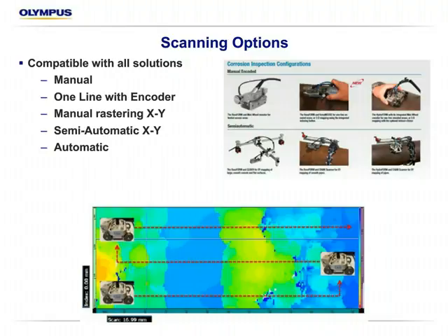And then we have more dedicated scanners, so link-based scanners for piping systems as well. Those are typically semi-automatic, in the fact that an operator will drive the scanner around the pipe and then use the indexing features to move it over a certain set index and then scan around again until the entire area is scanned.